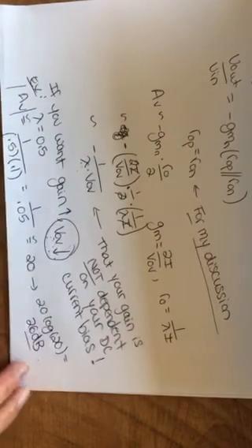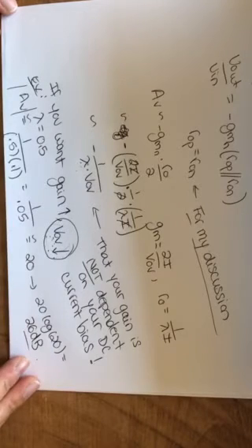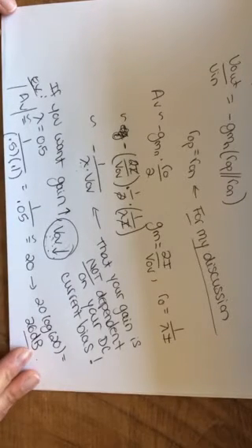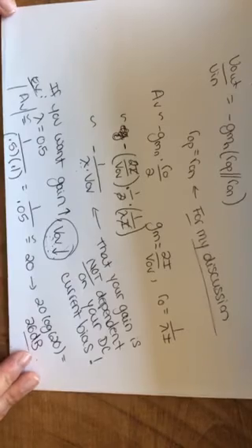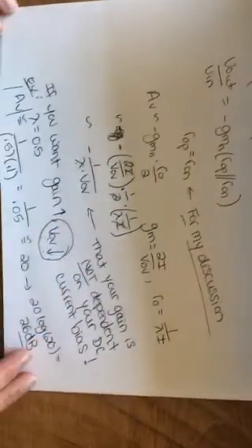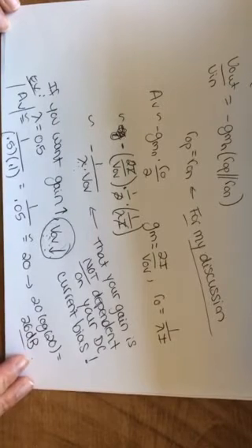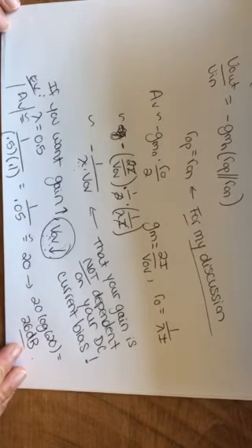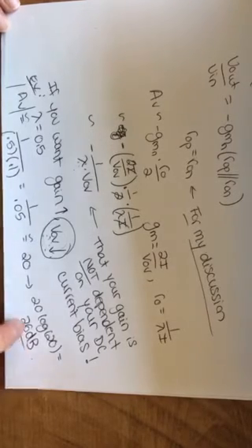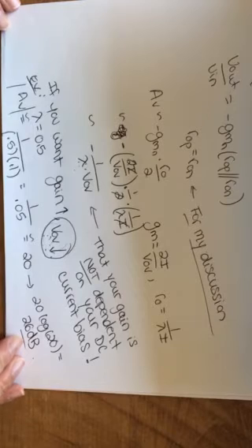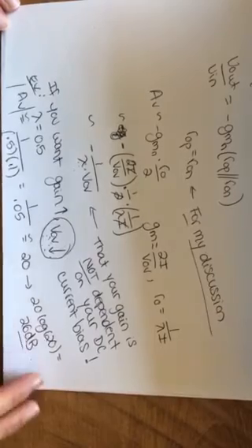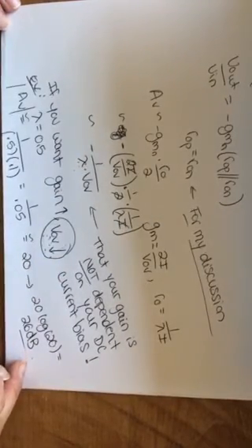You should have no problem getting the gain. Actually, as a matter of fact, your small signal gain will be higher than this 26 dB value in your circuit if you choose the correct DC bias and your correct width. Okay, so as long as you're biasing correctly and you've chosen a width based on your calculation from your DC analysis that we just did, you will have over 26 dB gain easily in this circuit. It is okay to have higher than 26 dB gain. So you do not have to set your gain to be exactly 26. The spec was a minimum of 26 dB. So as long as you are over 26 or at 26, you are fine. Okay, don't try to tune your circuit to get exactly 26 dB. No need to do that as long as you're over the 26 dB.